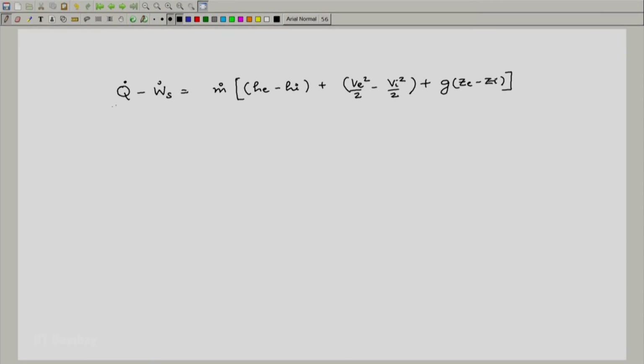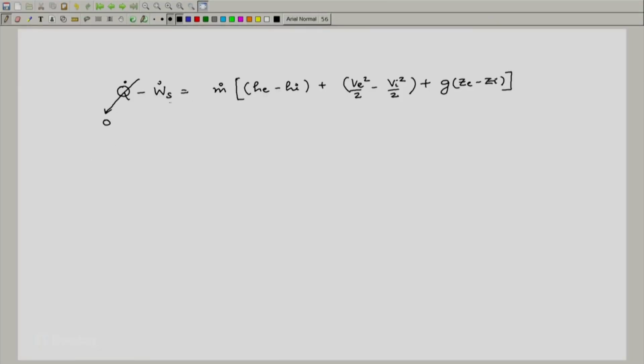And we realize that it is mentioned that the process is adiabatic. So, we say okay, this should be 0. We need to find this out. Whatever we get out of this is the actual work input. It will be a negative number since it is a compressor. Now, this is the work which the compressor will take in, and there is something given as the mechanical efficiency. That means there is an efficiency of transferring the power from the element which is driving it, that is really some kind of a motor, to the compressor, and hence the amount of power that is required will be more than this, and we will use the efficiency to calculate that.